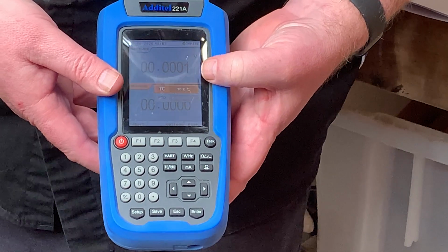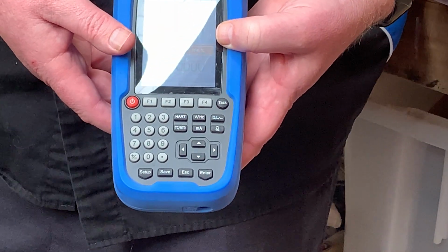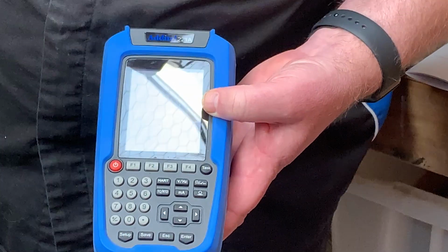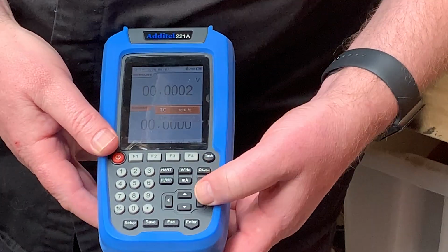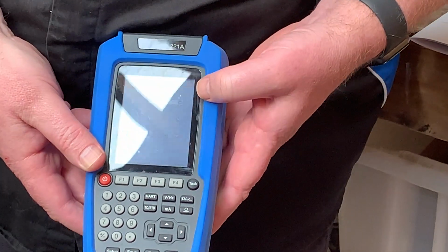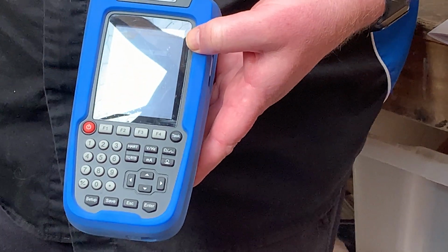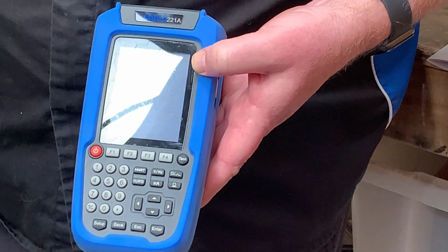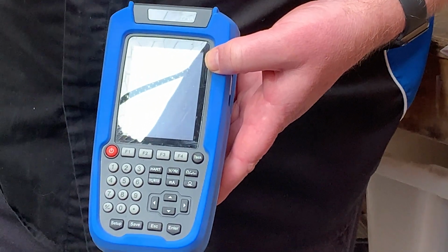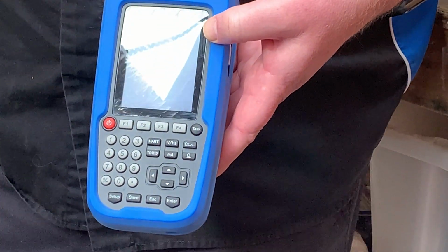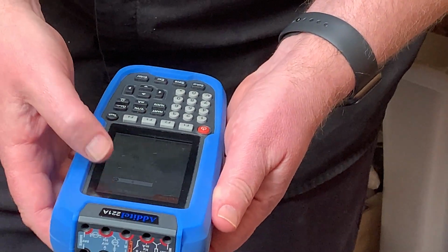Now it will default to type K because, as you know, in New Zealand that's by far the most common. But if you guys go and do some work at AW Fraser or something that's using metal, if you go use the cross arrow, you can select other thermocouples. So ST, all the exotic ones. In the plastic industry, T is common. In the molten metal industry, S or R is popular. So you can select any of those. But in 90% of the cases, you're going to be type K.